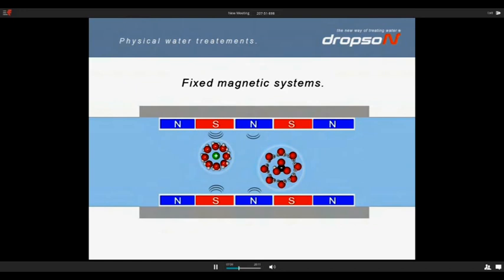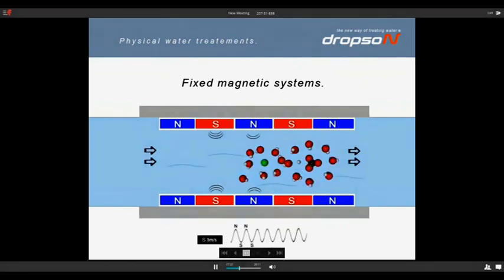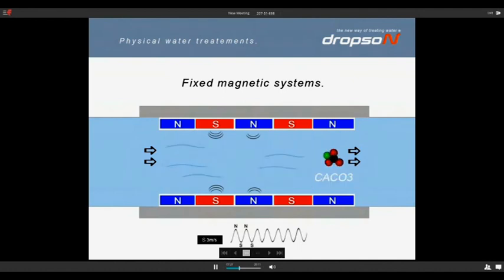In the pipe, the ions travel with the water flow. They will find themselves successively flowing through a north pole, south pole, etc. This successive polarity switch in the magnetic fields will disrupt and break the solvation spheres and free the calcium and bicarbonate ions to create non-encrusting microcrystals.